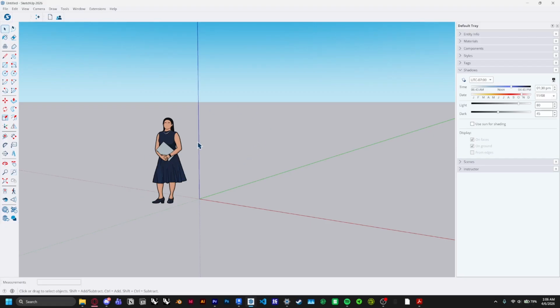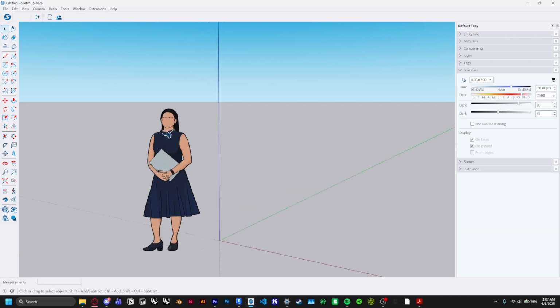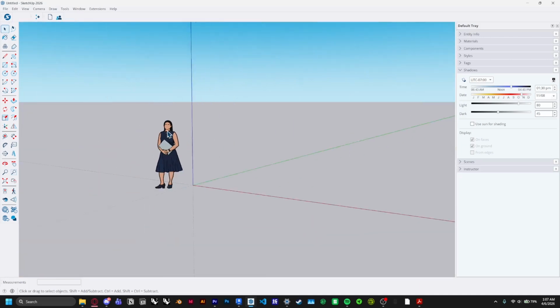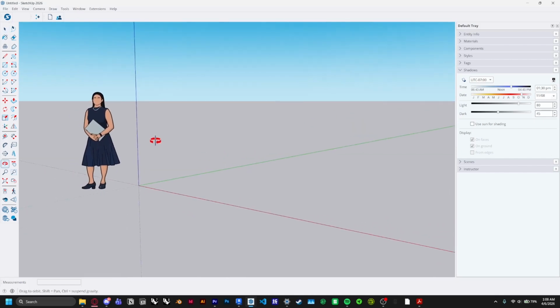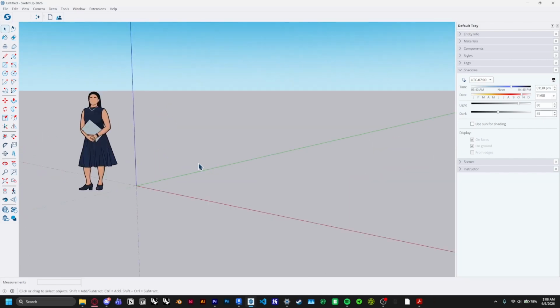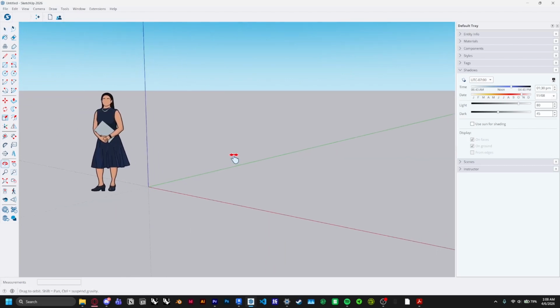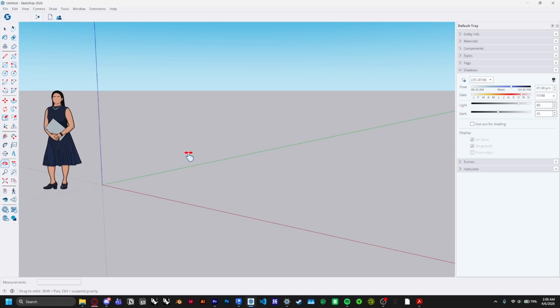It will load itself up into this view. And we'll go ahead and get started with learning the basic movement commands. The first one, and arguably the simplest, is zoom by using scroll. So move your scroll wheel back and forth. Secondly, if you click and drag on your scroll wheel, that will rotate your screen around. Third, if you press shift and click and drag on your scroll wheel, you will be able to pan around